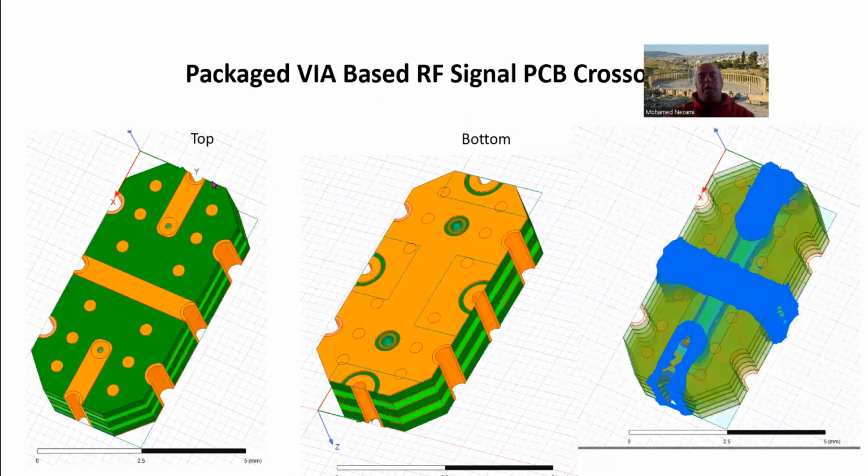And then we designed another one. We went further and designed a packaged one, not to compete with the Zinger or the Anaren and the AVX off-the-shelf crossover devices, but we did it the same, except it's packaged now. It's a 3D package where a signal comes in through PCB pads on the bottom, and then travels to the top to propagate, to crossover from this side.